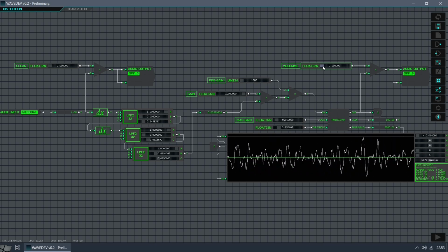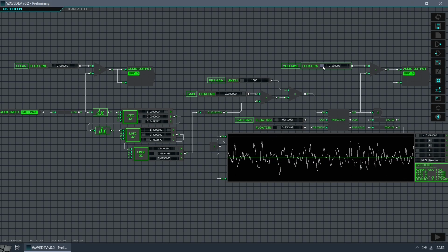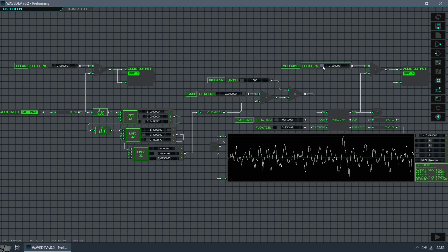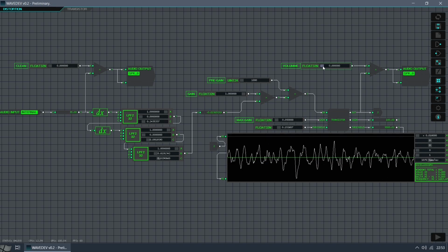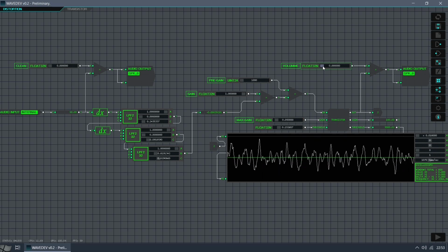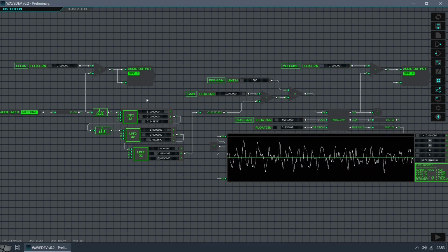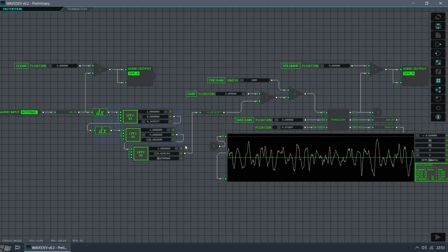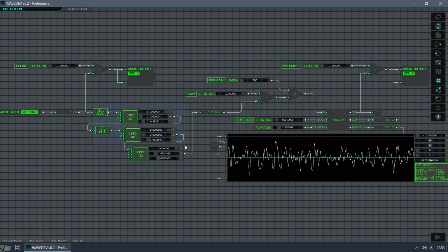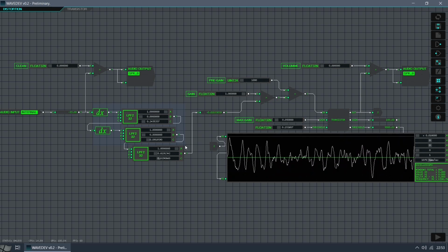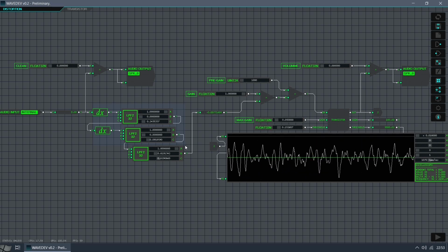There is a radical improvement compared to the first audio test. We begin to perceive the genuine sound of distortion. Although there are still things to correct here. It may have sounded a bit harsh to some ears, but it has to be. We are listening to square waves that are very intense in harmonic content. Remember that we heavily suppress the low frequencies, so there is no bass in the sample. That results in high-frequency components dominating the signal. Later we will filter this to give more definition to our sound.